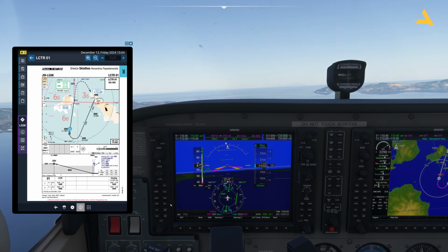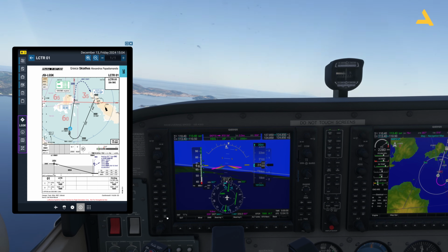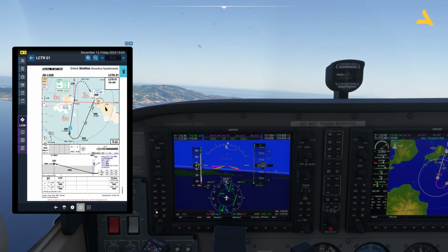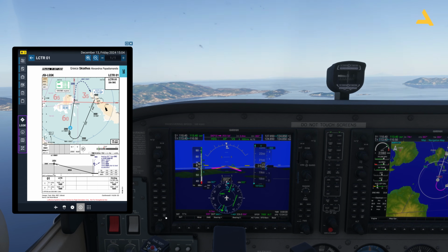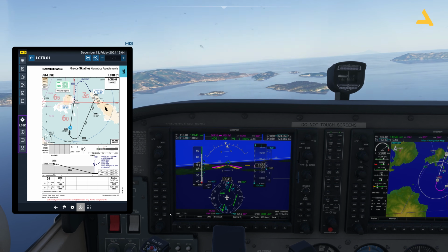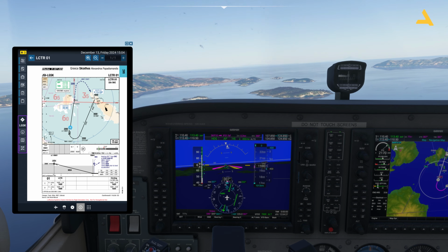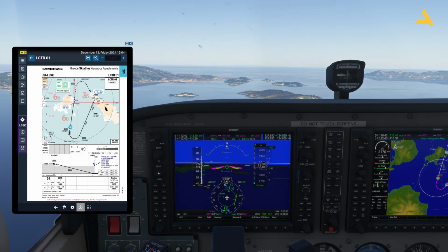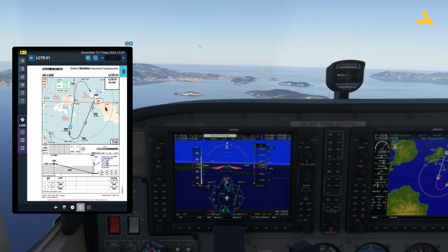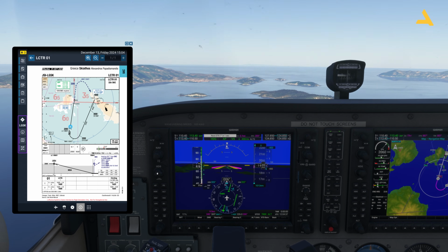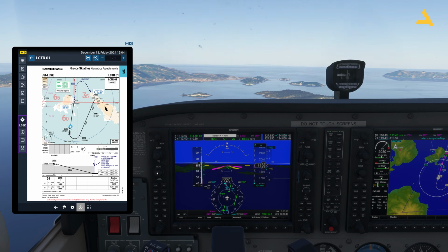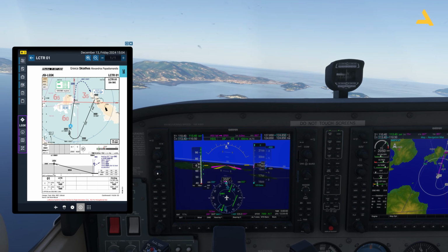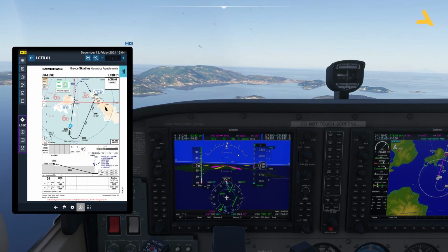And with this, I can start the descent and reduce the altitude. I can keep it at 400 and reduce the speed. Now, as the plane is not aligned with the runway, at any time you can disengage the autopilot and try to land the plane yourself, or what you can do is keep on adjusting the heading till you are aligned with the runway.